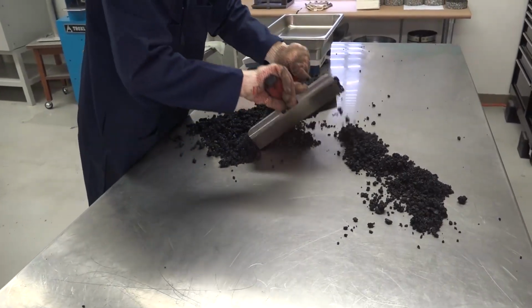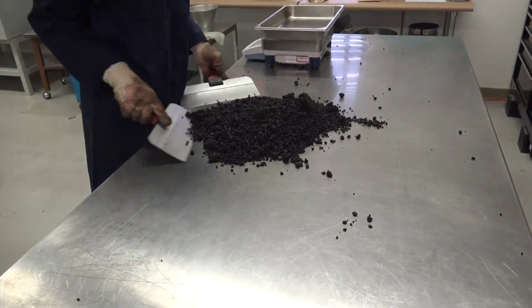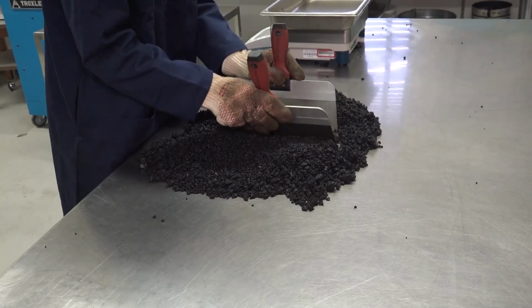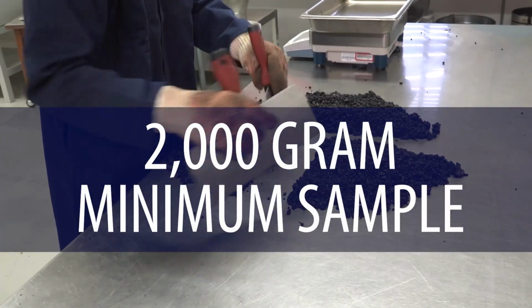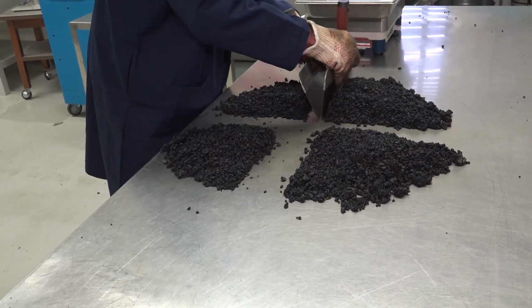Once you have your 6,000 gram minimum asphalt sample, your first step is to split and quarter it down to the correct minimum sample size. In this case, refer to Table 1 in the test method DOTD TR327, which requires a minimum of 2,000 gram sample for a 3/4 inch nominal maximum aggregate size mixture.